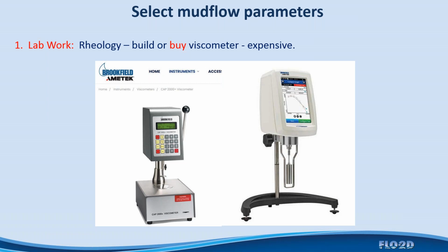And that's on the order of 1/10 inverse seconds, or about 0.1 inverse seconds. So what you don't want to do is get a viscometer like this, or like the one that I built, and crank it up to 100 inverse seconds, or some higher rotational speed, because all you're going to do is have slippage in there. It's not good.